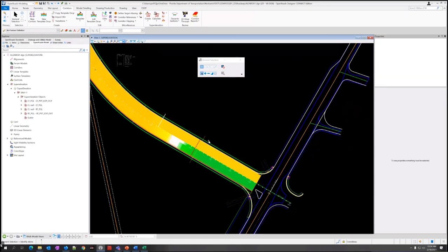All right, so we're going to do exercise 3.8. Take a look at the super elevation editor. So that's up in this little tool right here in the right corner of super elevation. It's well hidden. So click the drop down because it's not the first tool, so it may not be the option that's selected. The second option in the list is super elevation editor.